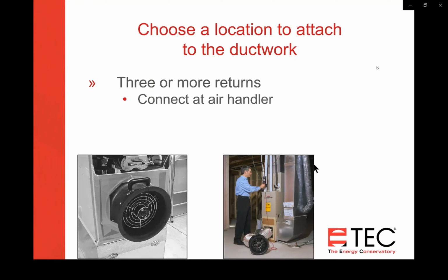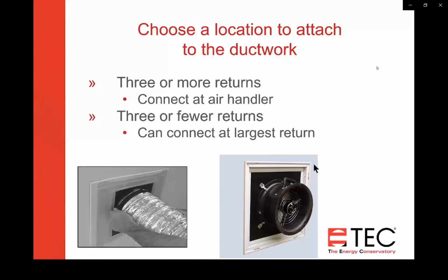If you need more airflow, the flex duct does restrict the flow, which certainly doesn't change the pressure, but it does restrict the total flow somewhat, because it's adding more resistance. But you do have that option of connecting directly to the air handler or using the flex duct to connect to it. If you have 3 or fewer returns, you can connect at the largest return. And again, if you're pressurizing, you can connect the fan directly there.